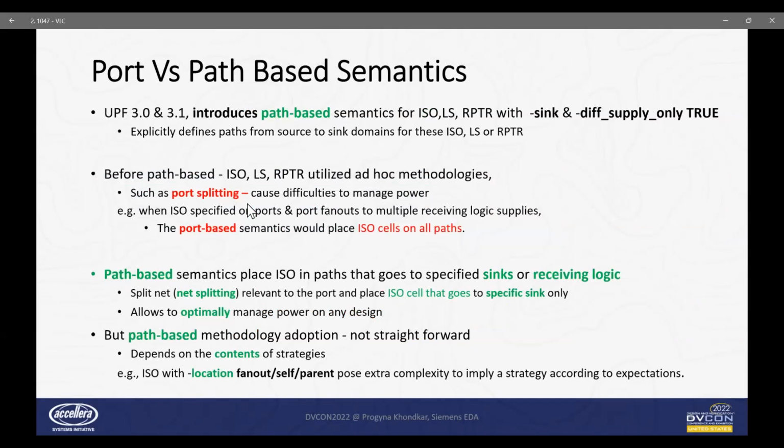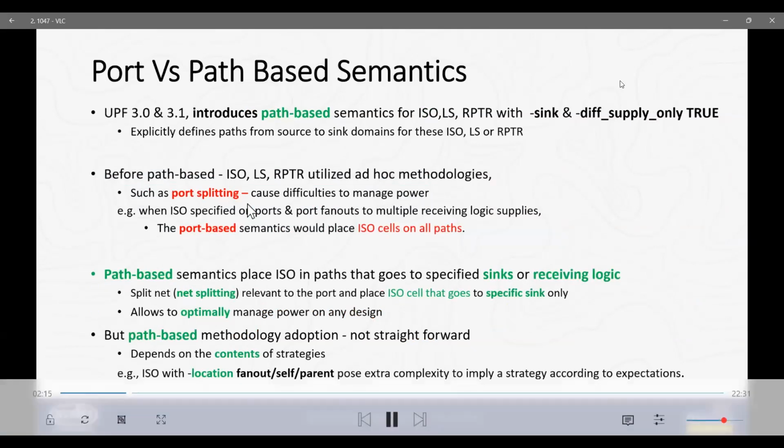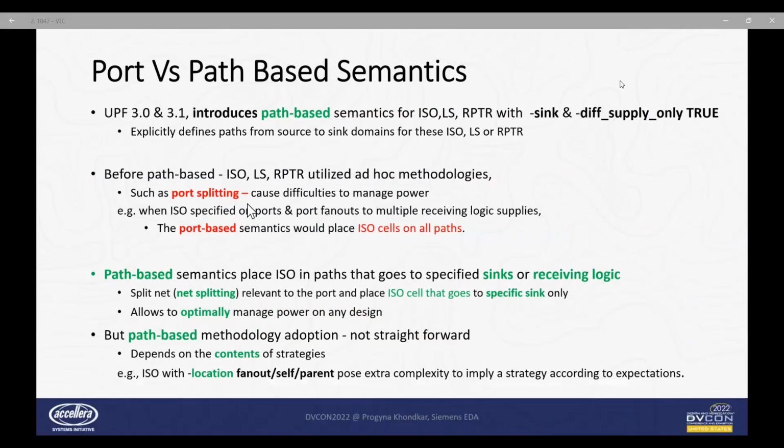In this slide, we will talk about port versus path-based semantics. In fact, UPF 3 and 3.1 combinedly introduce path-based semantics for isolation or other strategies in conjunction with -diff_supply_only true commands from UPF. These in combination explicitly define paths from source to sink domain for these strategies.